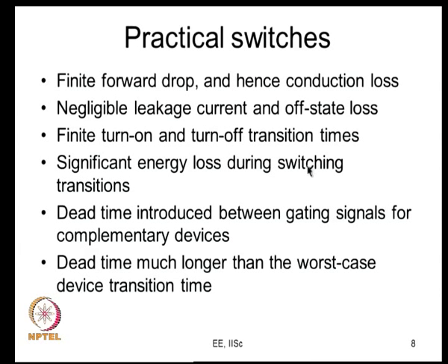One consequence of this is that a significant amount of energy is lost during switching transitions. We focused on this over the last couple of lectures. In one lecture we tried to see how to evaluate this loss, in the other the focus was on how you would design a PWM method which will reduce the loss, or how you will compare the switching loss between two methods. So, this is one consequence of the turn on and turn off transition times being finite.